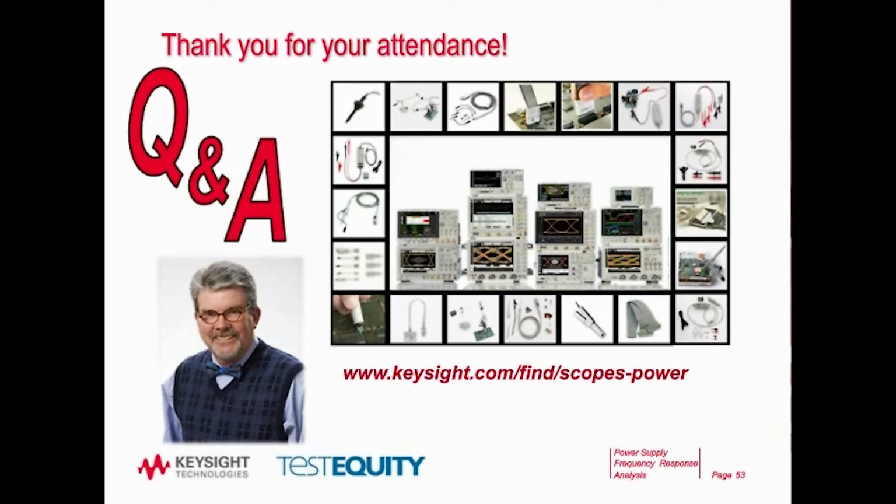You could do that. And the one-to-one probe is almost effectively that. It depends on what you're going to terminate into. If you terminate into 50 ohms, then you've got to figure out whether or not 50 ohms is going to load your signal that much. Or you could terminate into 1 megohm, but if you terminate into 1 megohm, then you limit the bandwidth. So SMA into 50 ohms, and if you can install an SMA connector down on your board, that would give